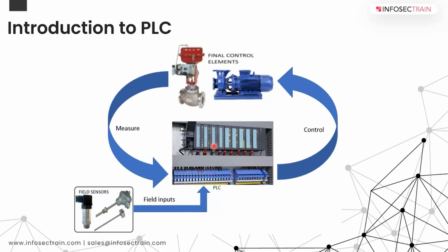And from here, these IO modules may not all be the same. It can be 8-bit, 16-bit, 32-bit, and there might be analog IO, digital input, DO, analog input, analog output modules as well, and sometimes resistance for an RTD or a thermocouple.